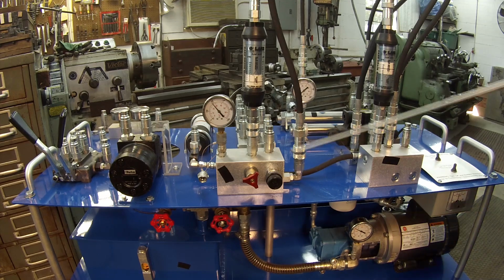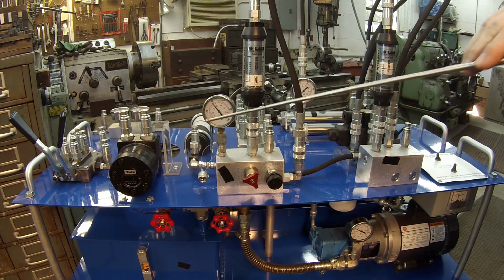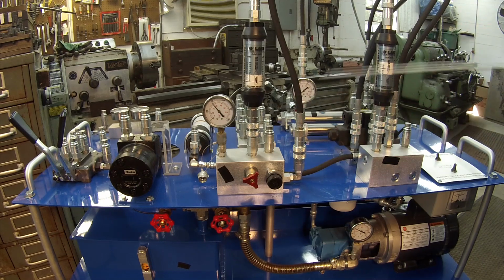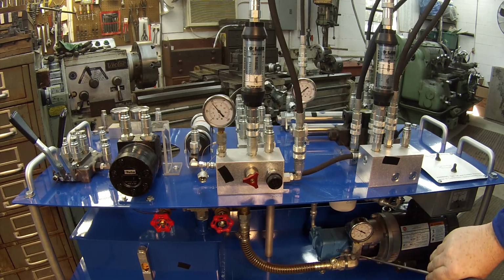You have to have these devices in your system to be able to figure out what's going on in any hydraulic system. Same thing with your hydraulic motor. If your motor is turning and it slows down, then you are losing flow in your system somewhere. And again, you see that this pump is pumping 1.8 gallons per minute. If that drops to 1.0 gallons per minute, that means something's wrong with my pump.